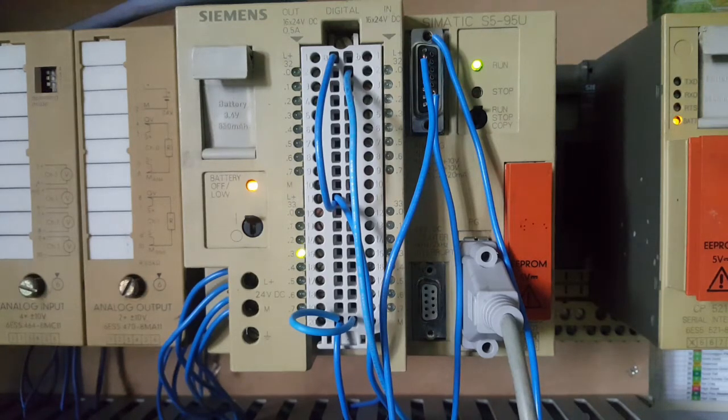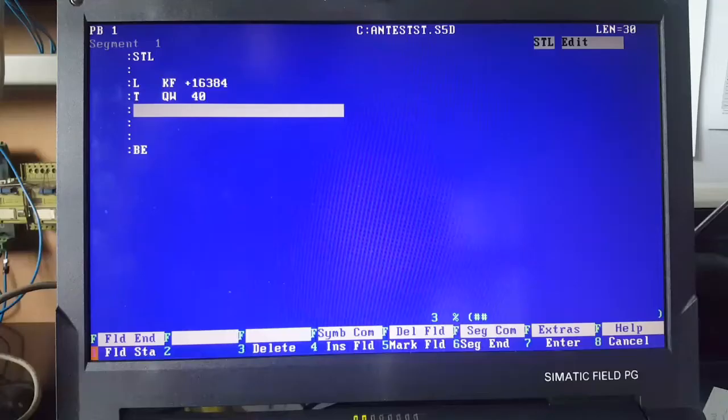0.0097 volts per step. This means that for every 0.0097 of a volt you put into the analog input, the binary value will increment by 1. So for example, if you want 5 volts to be output from the analog output, you could divide 5 by 10, which gives 0.5, then multiply this by the maximum binary output, which is 1024. This gives a result of 512. So if you write a binary value of 512 into the analog output, you should get 5 volts.